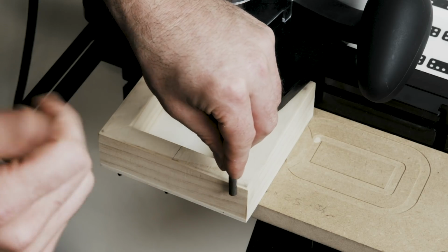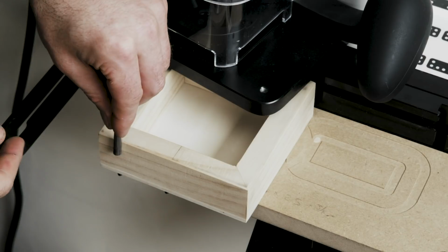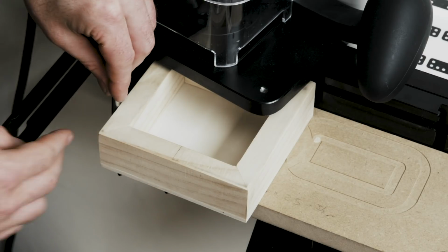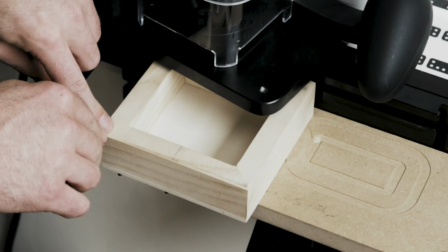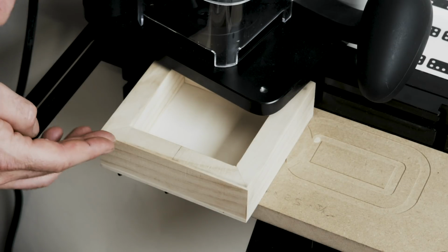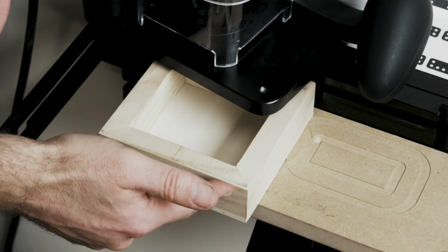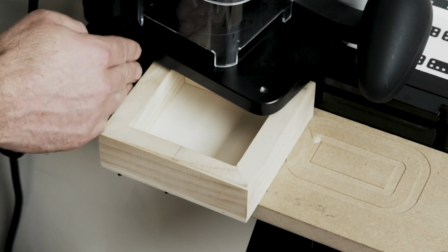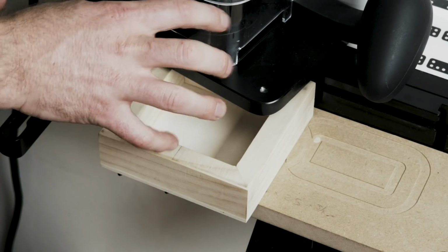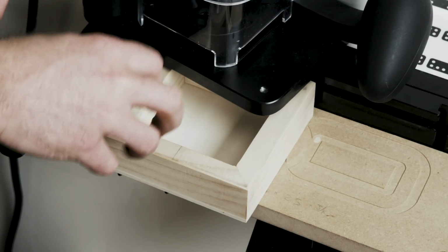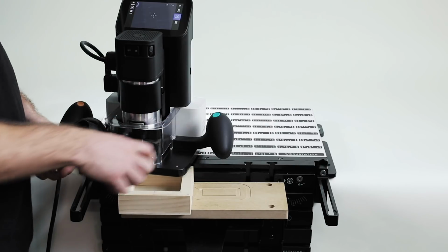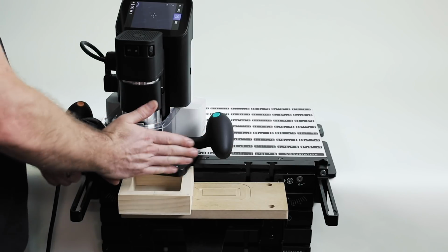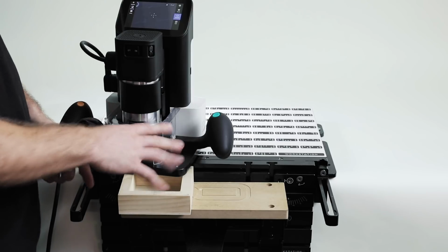So just lightly touch and click probe, and then move over, lightly touch again, and we come around a corner to get our y-axis and probe there. From that point on, we have a clear reference at 0 along this face and 0 in y along this face. So we can then place elements relative to that position, so an inch in from either axis or in the center here, however you want to do it, and know that it's always going to be aligned. Its orientation and its position will be explicitly tied to this edge.